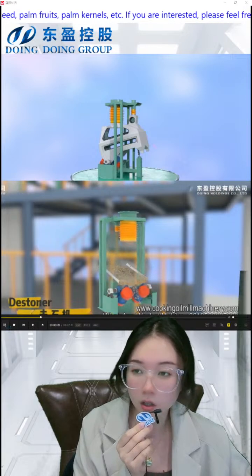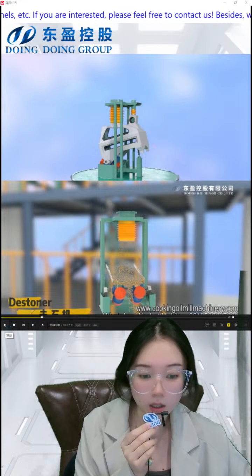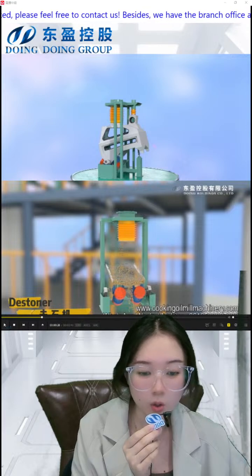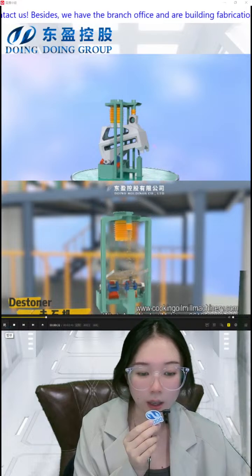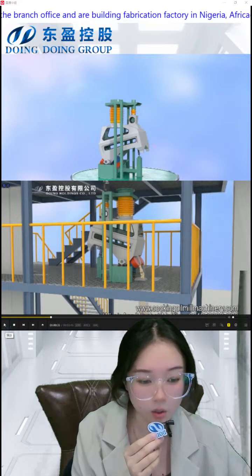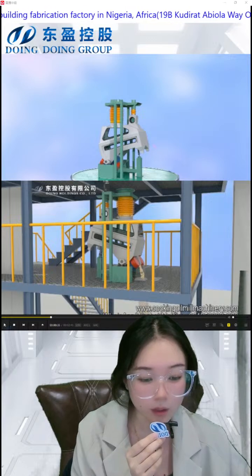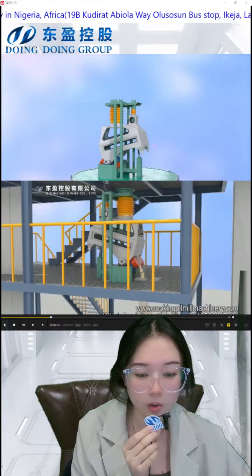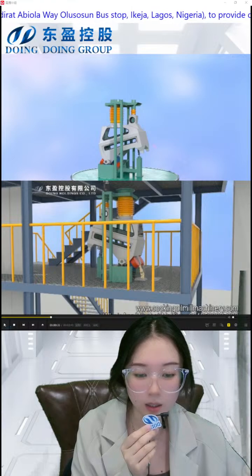It is the destoner, a specific gravity stone removal machine, which is mainly used to remove small but relatively hard impurities such as soil and stones from the raw materials. Based on the weight of the stones and the raw materials, a unique sieve plate and wind force are designed to remove these impurities.